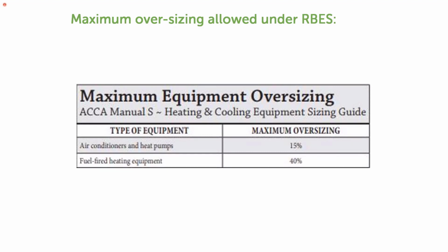But if that building's maximum design load is really only, say, 50,000 BTUs, you have a system that can still meet the load at 50,000 BTUs, but is massively oversized for the majority of the heating season, which has significant impacts on equipment performance and overall energy use.